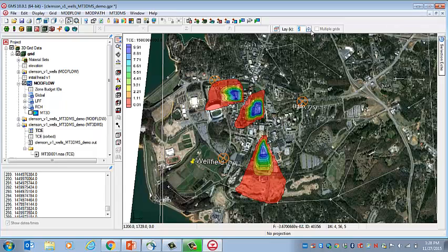So they're moving down vertically and then spreading horizontally, and the dispersion causes the concentrations to decrease. Nevertheless, these are the concentrations here. 0.01 milligrams per liter is still above the MCL for TCE. So if these really were TCE plumes, this would be contaminated water that we would have to deal with.